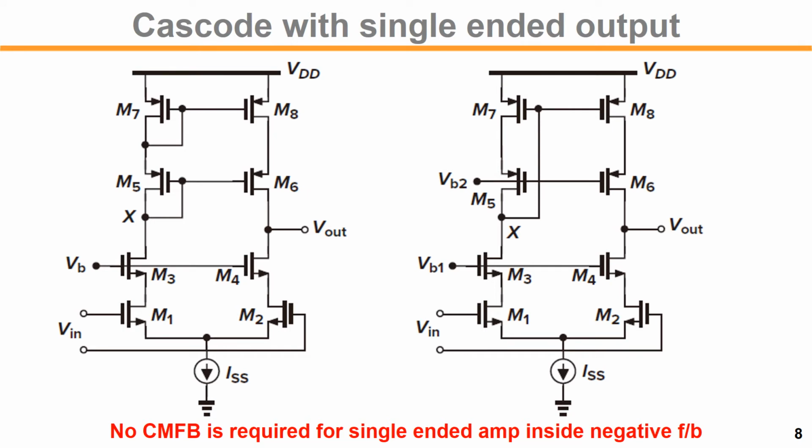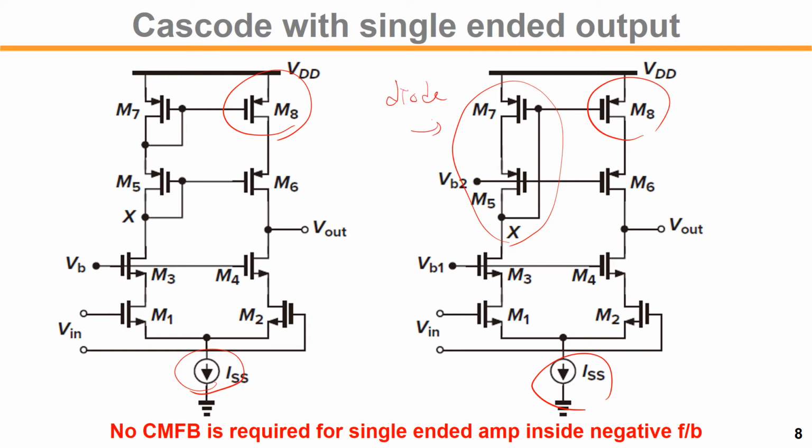This is a cascode single-ended output. For this kind of circuit, as you see here, we have the current source and current source one here and there. But the other side is what? This is a high swing cascode. This is the one with the diode connected load, and on the left hand side also. The impedance looking into the diode connected load is low compared to the output impedance of the transistor, RO. So in that case, this node voltage is well defined, right?